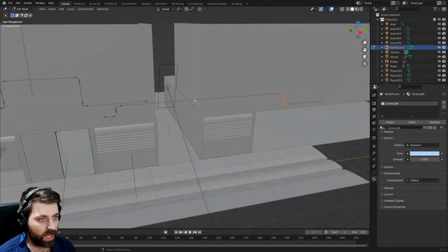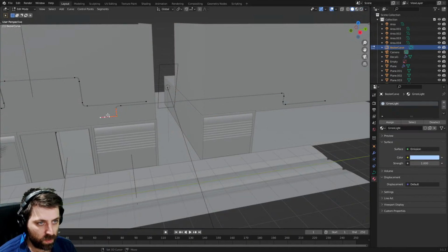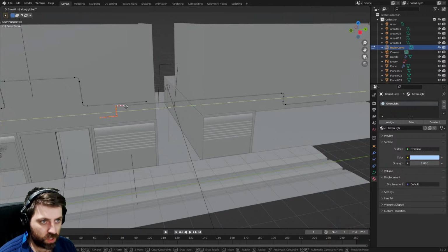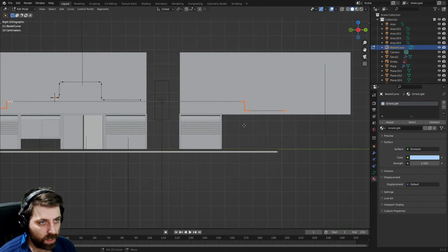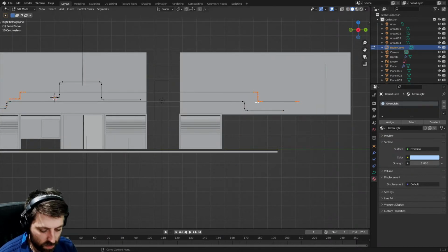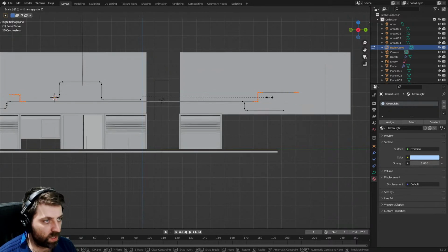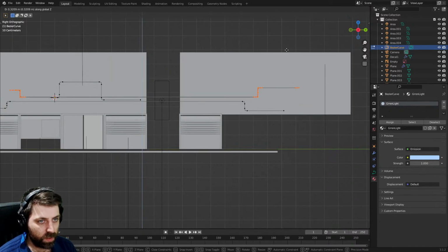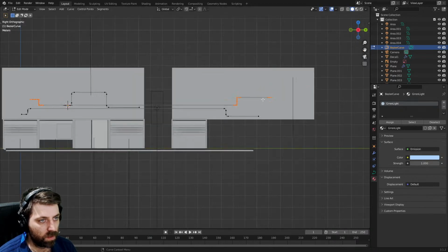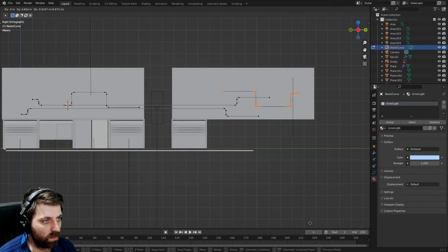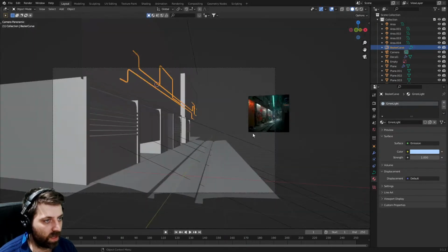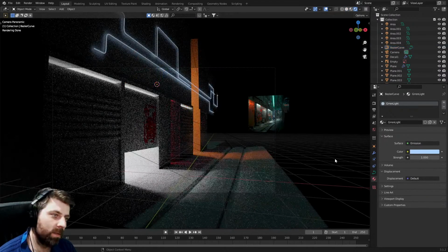All right, let's go ahead. We're just going to keep working on those lights a little bit more. GY, I'm just going to whip that all the way across. Let's go Shift D, scale Z -1, just so it's kind of flipped up a little bit. We'll grab this piece here, Shift D, rotate 180. And then we've got something like that. What is that looking like? That's not bad. I'm down with that.